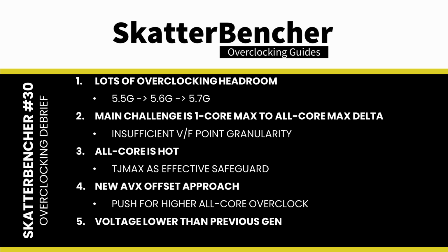In terms of voltage, it's important to note that they're much lower than what we're used to on previous Intel platforms. Whereas on Rocket Lake we'd see over 1.5 volt even at default, on Alder Lake the default voltage ranges up to 1.3 to 1.35 volt.